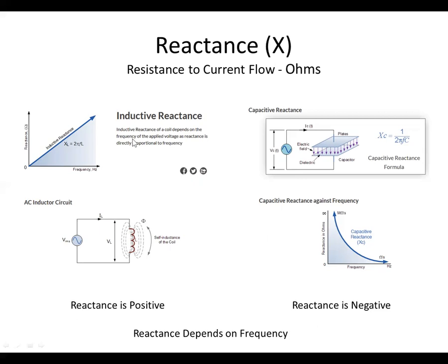And then as you increase the frequency that you're driving the inductor with, the reactance increases linearly, like is shown here, and the calculated value is 2 times pi times the frequency times the inductance. So 2 and pi are constants. Pi is 3.14. The inductance is determined by the design of the inductor, and then you multiply those products by the frequency, and you'll have increasing reactance.